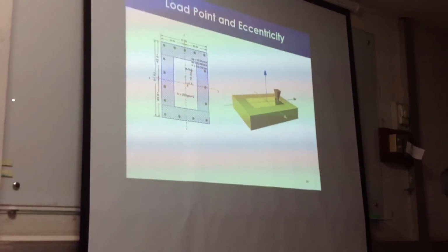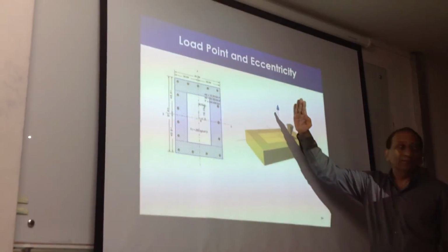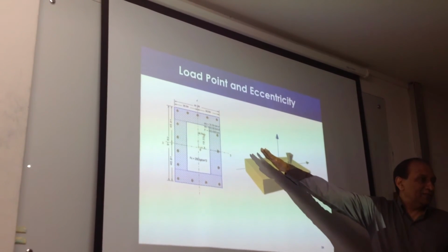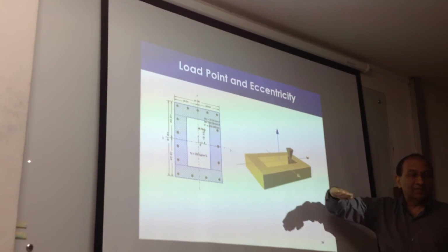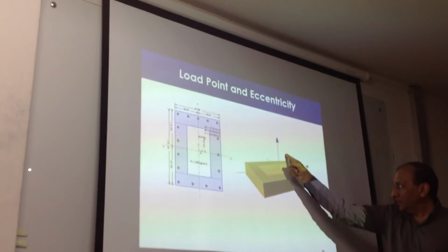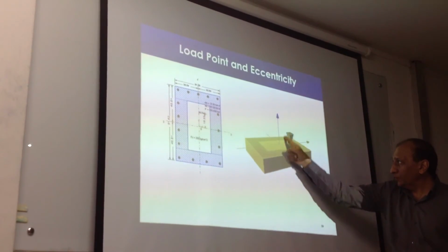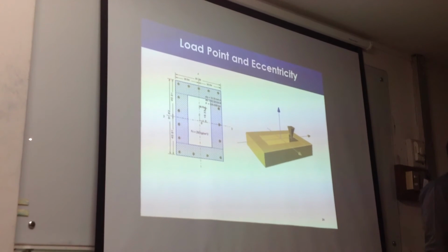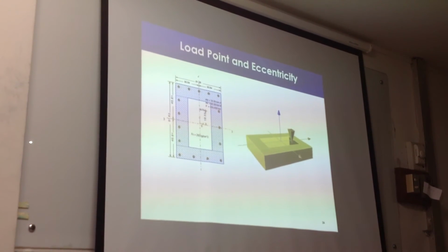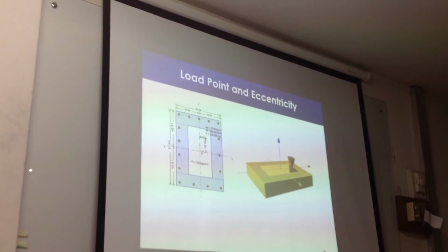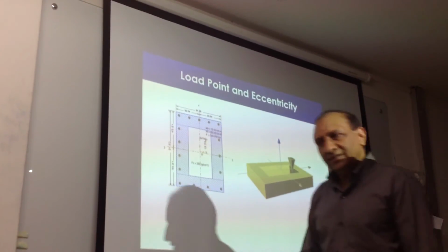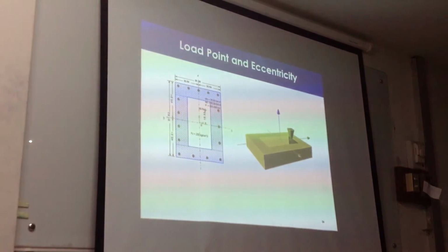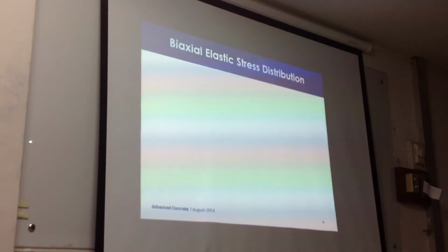Right? Because when it goes down, it will lift up the cross section in this direction, and it will press the cross section this direction, so the strain profile, and there will be a line perpendicular to this somewhere here about which the cross section will rotate or deform. And that normally we call neutral axis, right? But we will learn later that that is not really the case.